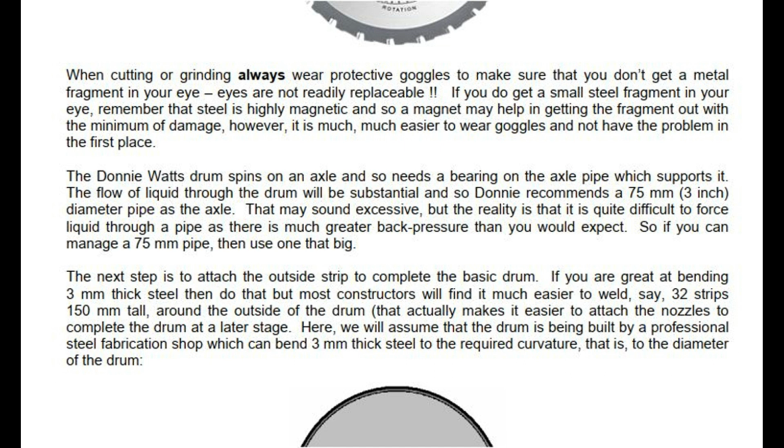The next step is to attach the outside strip to complete the basic drum. If you are great at bending 3 mm thick steel, then do that, but most constructors will find it much easier to weld, say, 32 strips 150 mm tall, around the outside of the drum. That actually makes it easier to attach the nozzles to complete the drum at a later stage.